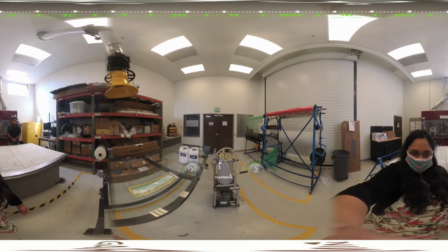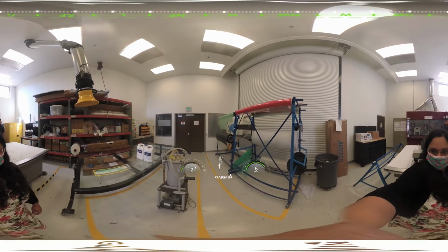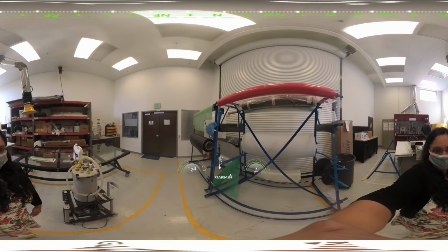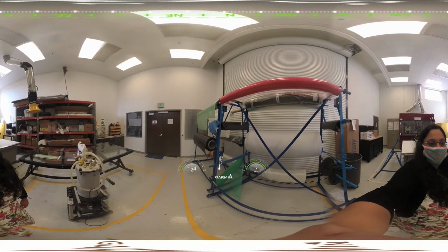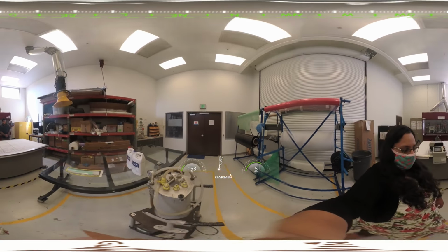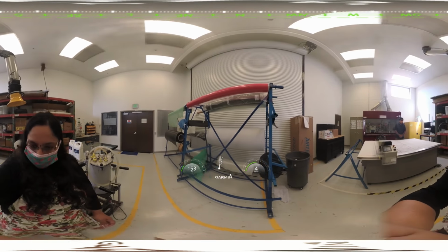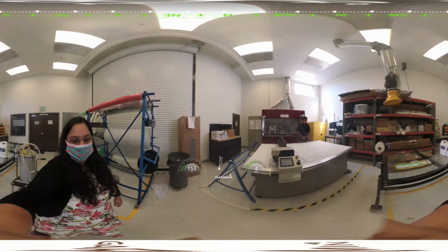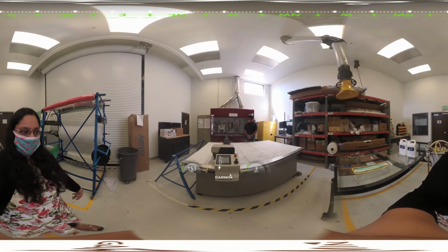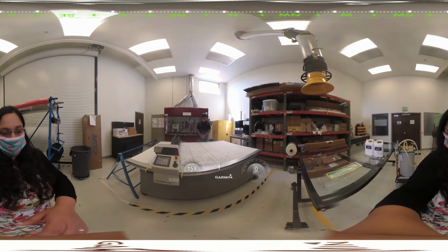In the case of VARTM for the first lab, we are going to be using glass fiber fabric. As you can see, there are different kinds of fabric, glass fiber fabric, carbon fiber fabric. These are used widely in the aircraft industries. In our setup, we are going to cut these fabrics according to a model using the Gerber cutter. The roll is transferred from the rack here, and we're going to have a CAD program, and we're going to run it to cut the fabric.